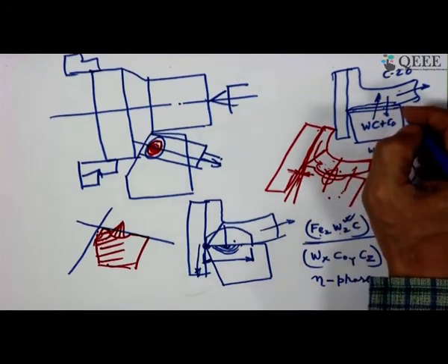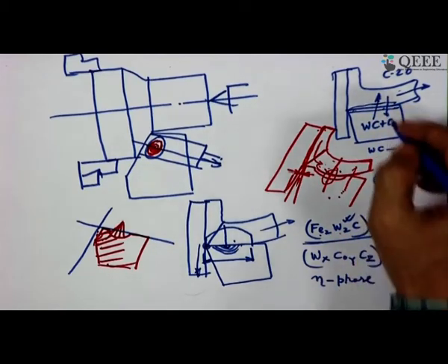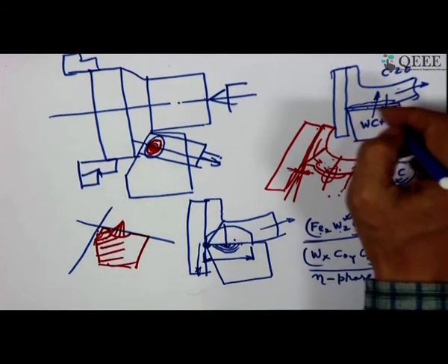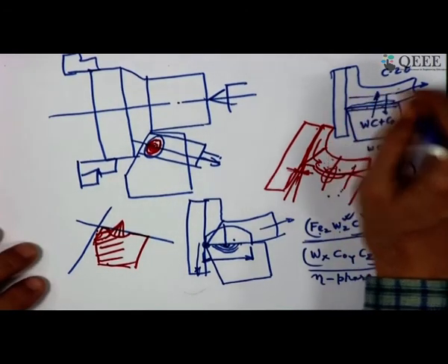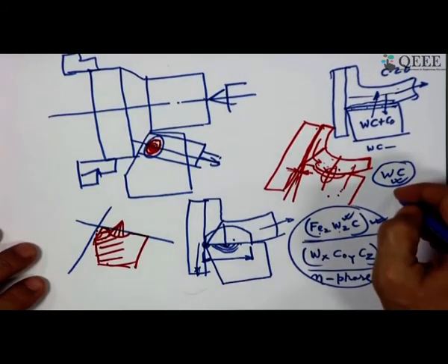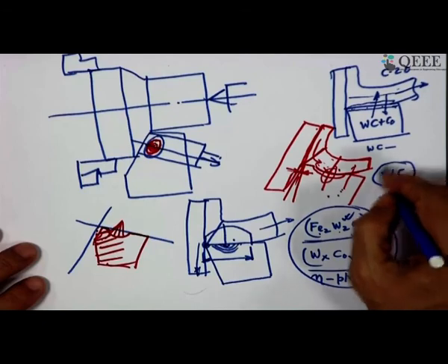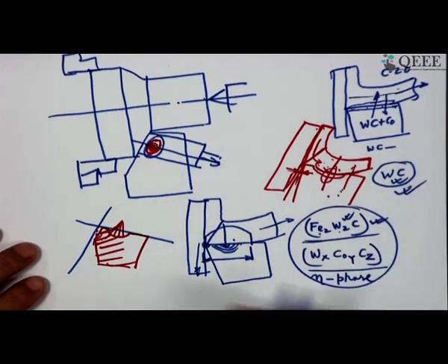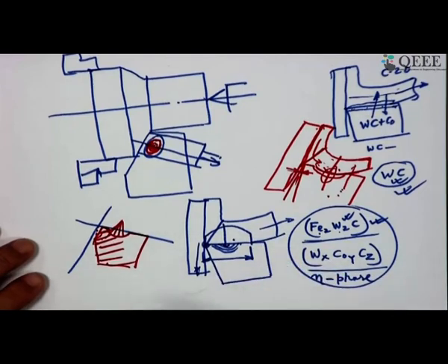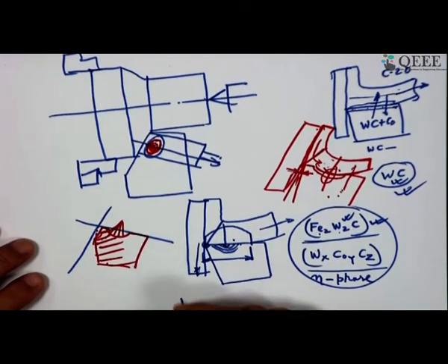So, first of all you have this layer on the tool, and beneath that you have this layer which is called the decarburized layer, deficient in carbon. Now, once that is formed, abrasion is also there. Since this material cannot possess the same wear resistance as tungsten carbide, this will simply be abraded, and this is called post diffusional abrasive wear.